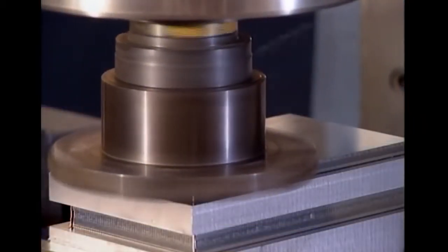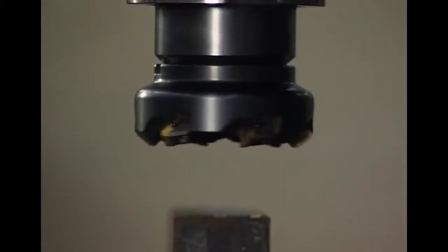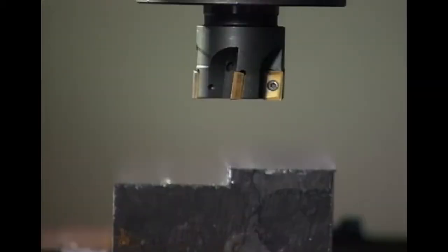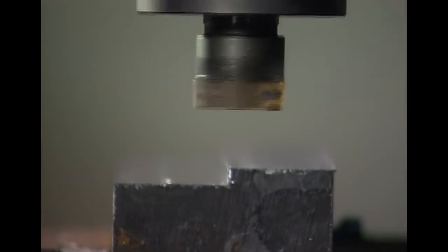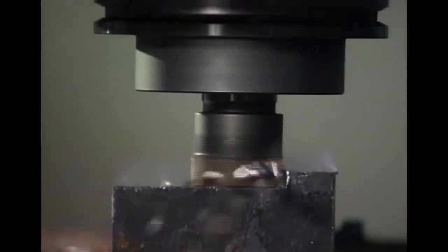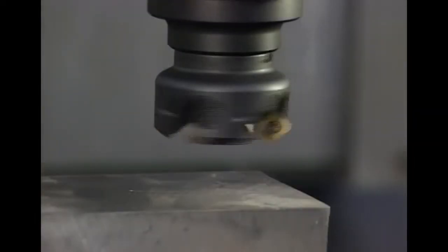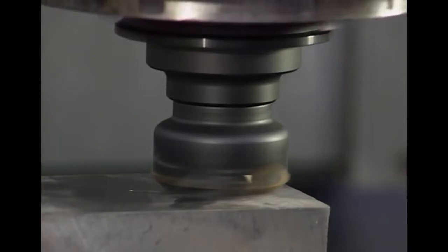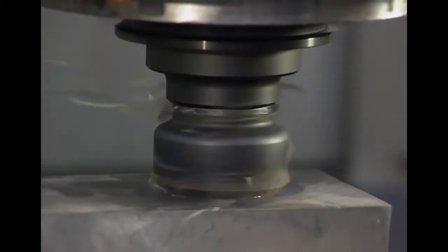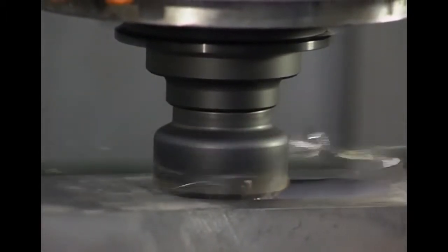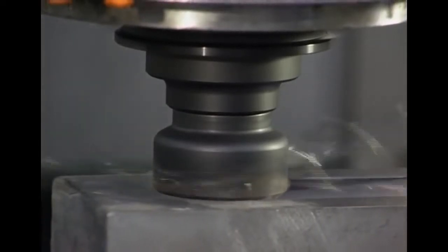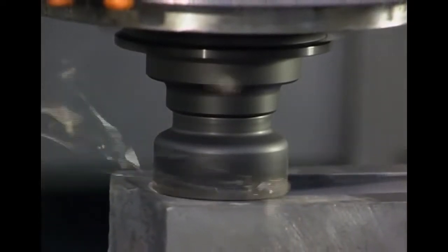The milled surface results from the combined action of cutting edges located on the periphery and face of the cutter. The flat milled surface has no relation to the contour of the individual teeth, except when milling a shoulder. Not all face mills are used for large, straight cuts. Some small diameter face mills are used to ramp into a surface, then plunge to a depth and interpolate outwards to mill a large pocket more efficiently than an end mill could.